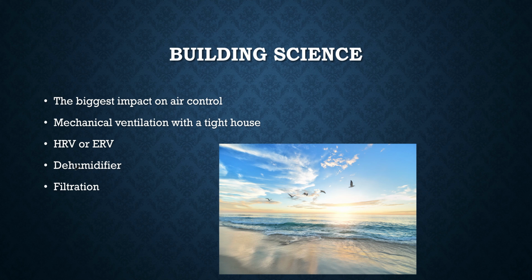So you're going to retain some of that energy that you spent a bunch of money pumping out of the house. You're going to retain some of that with the ventilation system. So, it's much more efficient. You end up keeping a lot of the energy. Now, the ERV is an energy recovery ventilator or an enthalpy recovery ventilator. You can think of it that way.